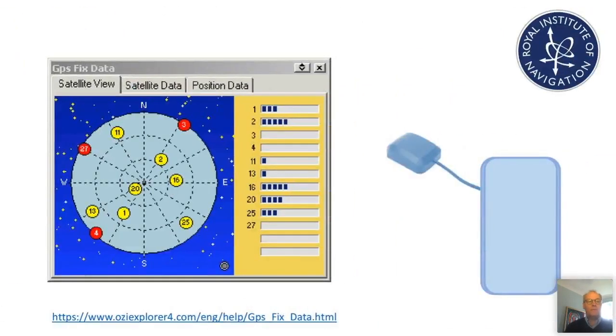And with somewhere between 24 and 30 satellites in each of those 4 GNSS constellations, a receiver on the surface of the Earth with a clear sky can typically see 7, 8, 9, 10, that order of number of satellites as indicated here. This is a sky plot from an antenna on the surface of the Earth looking at the GPS satellite constellation.